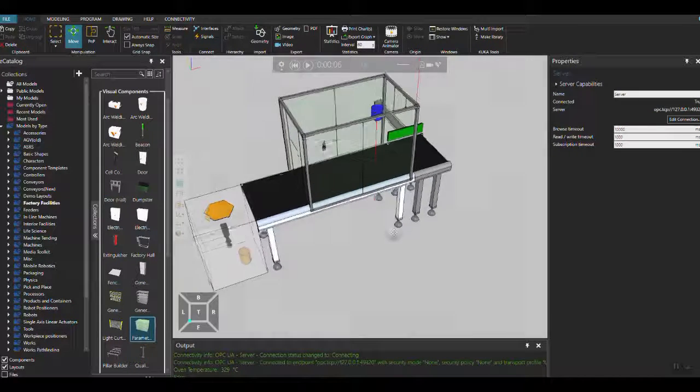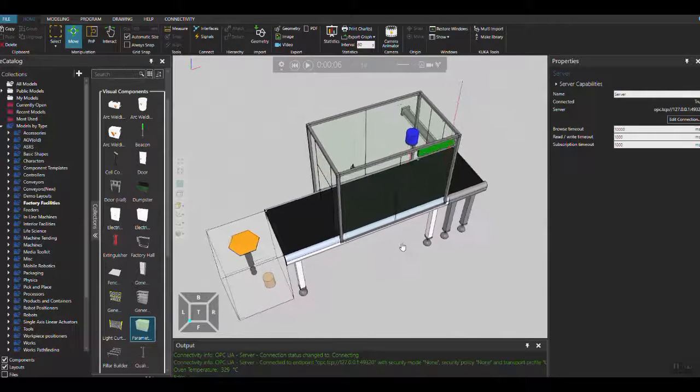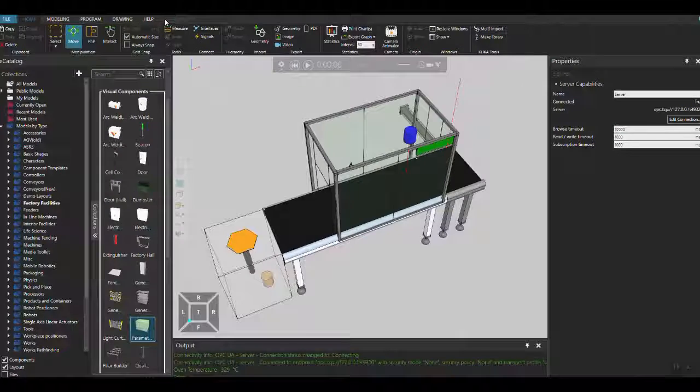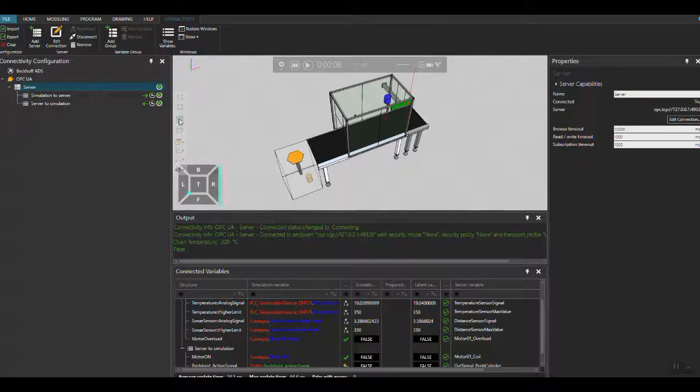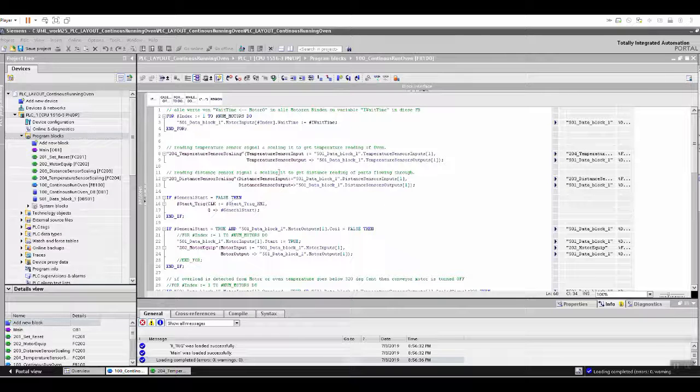And here, just to make this video short, I wouldn't go into much detail on the setup. We are all set to go here. The connectivity is ready. I'm connected to the CAP server. The CAP server is running here with all the tags, generated with absolute addressing for Siemens PLC. We have the Siemens code running here in this virtual machine.